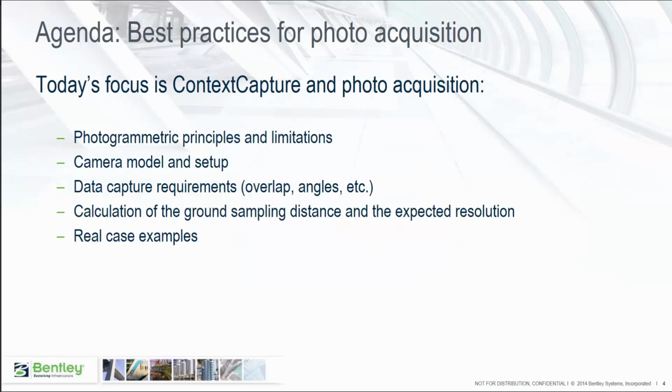Today's focus is ContextCapture and photo acquisition, photogrammetric principles and limitations, camera model and setup, capture requirements such as overlap, angles, etc., calculation of the ground sampling distance and the expected resolution of your 3D mesh, and some real case examples to illustrate the capturing process.